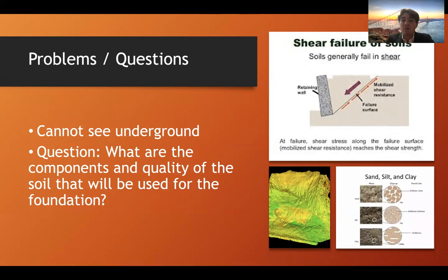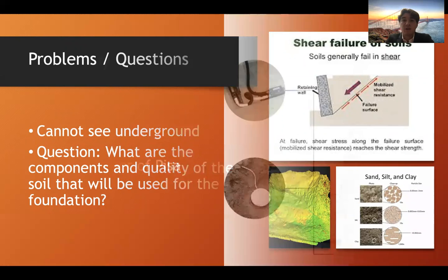A question would be the components and quality of the soil for the foundation, such as the shear strength, compressibility, permeability, as well as the percent of sand, silt, and clay within the soil, which would determine how likely it would be to shift or to change throughout the structure's lifetime.